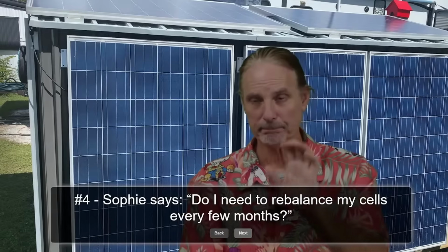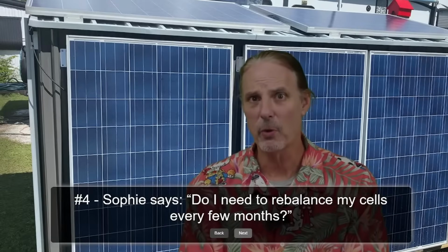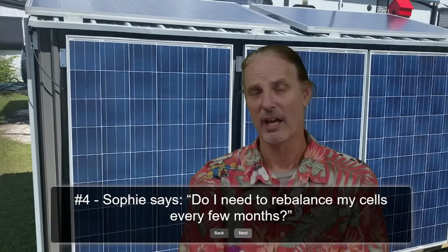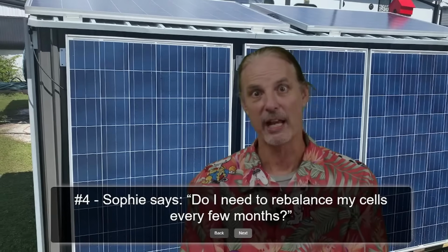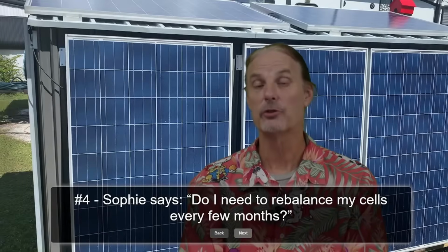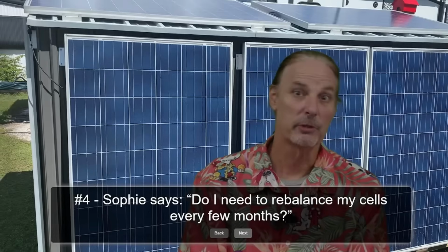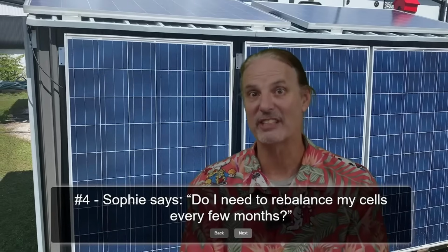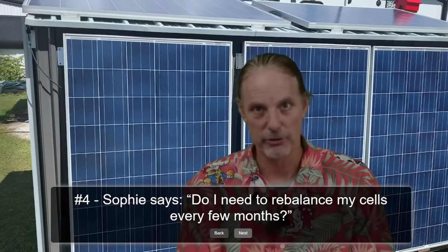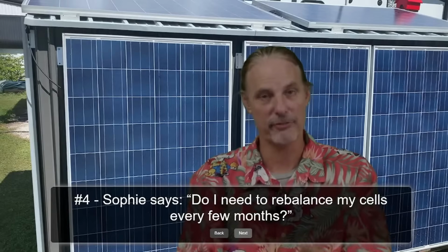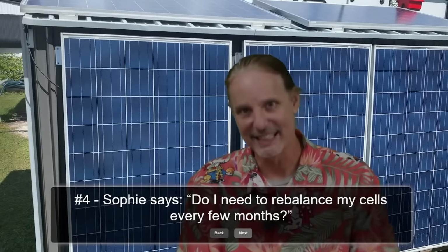Keeping in mind that if you're looking at, let's take my battery, the 304 amp hour JK BMS, that is 304 amp hour cells, and at 2 amps, it is going to take quite a while to pull enough voltage out of one and give it to another to balance a bank of 16 cells. And so the smaller the battery, obviously, the faster this would go, and the bigger the active balancer, the faster this would go. All of them work, but they all take time to get to that point.